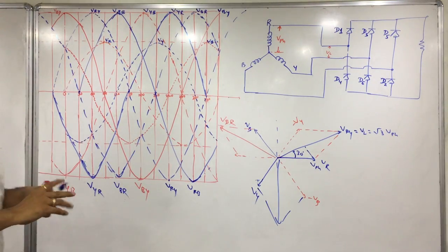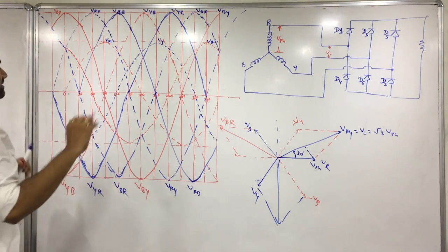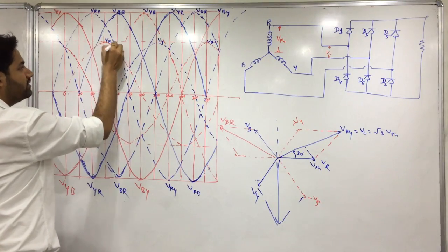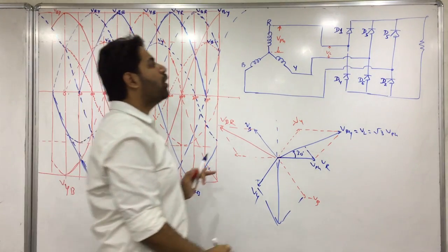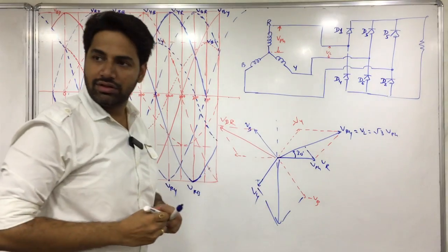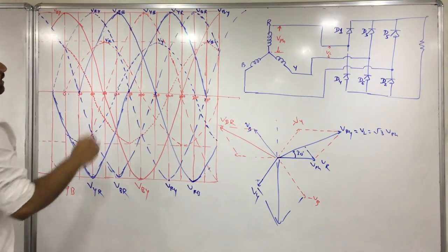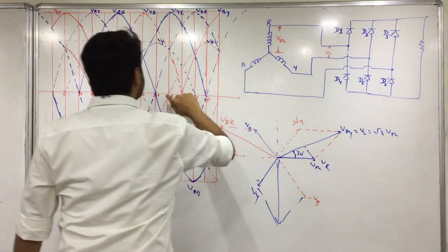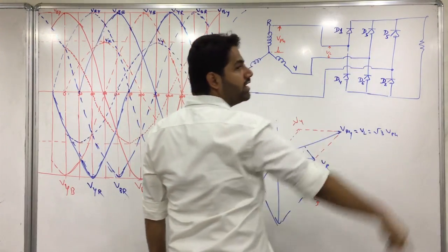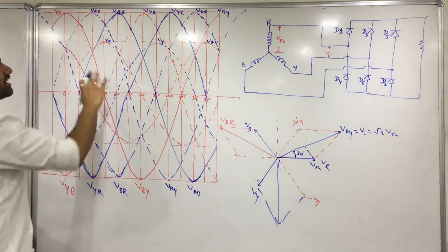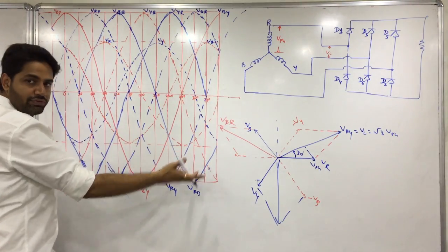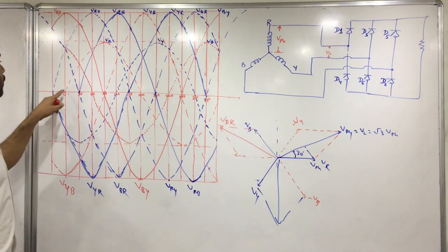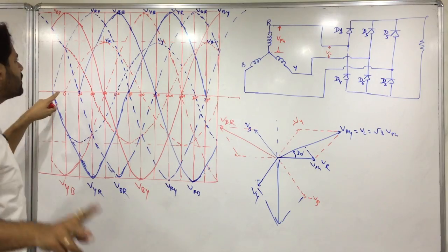So you should not forget your phase voltages as well. See, phase voltages are like this. Can you see R voltage? Okay. When R voltage is positive, D1 will conduct. Yes or no? Okay. Fine. When Y voltage is positive, D3 will conduct, and when B voltage is positive, your D5 will conduct. Fine. So these are the positive groups, these are the negative groups. Now let's say when you started from 0 instant, everyone should be concentrating on two